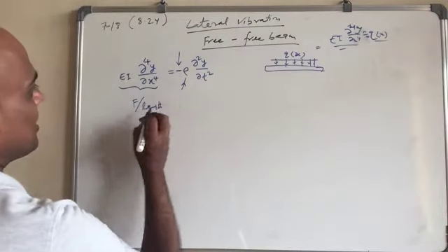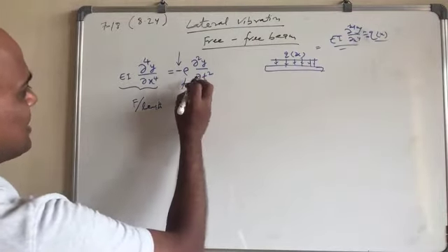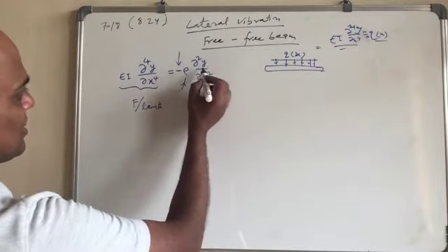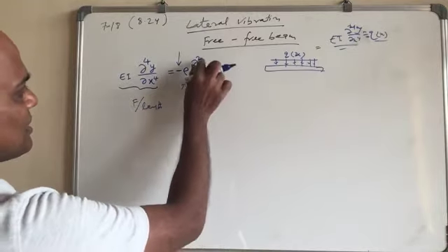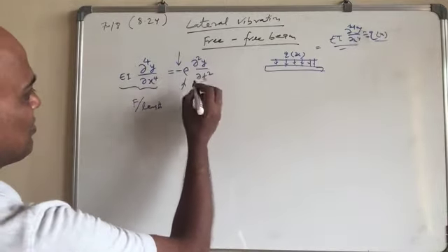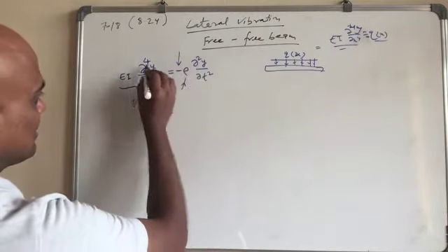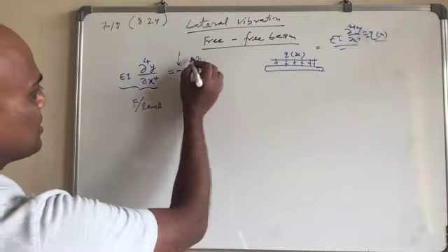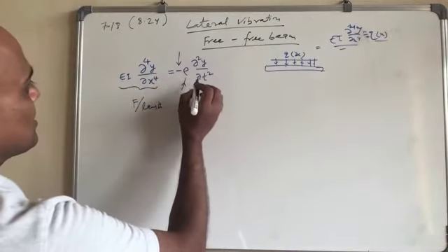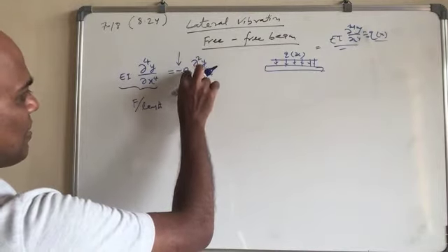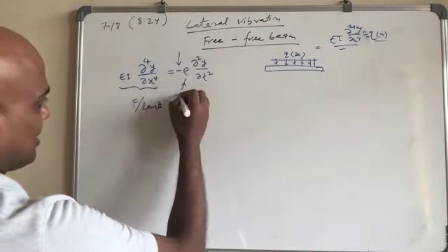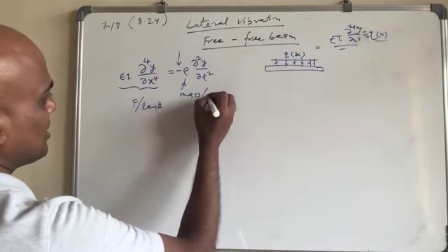And what you see here is acceleration. So mass times acceleration is the force. So this should be in terms of force only. Since the whole thing is force over length, this is force per unit length. Hence, what you get is this should be mass per unit length.